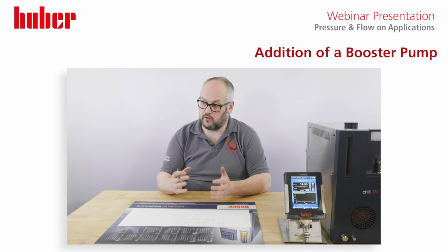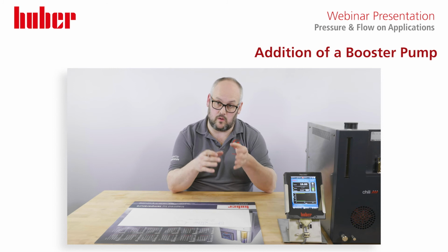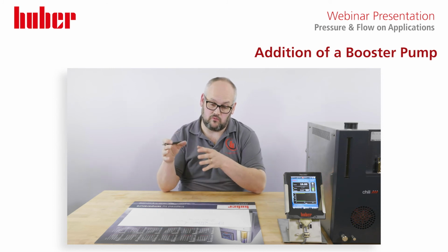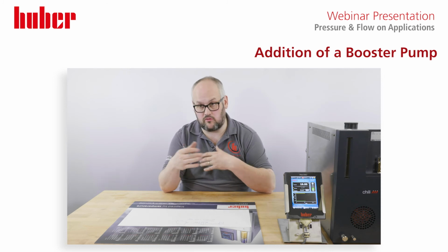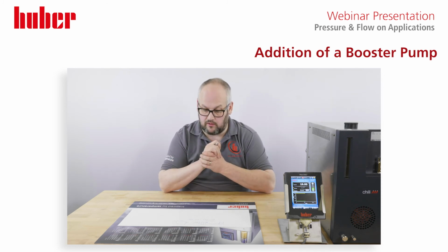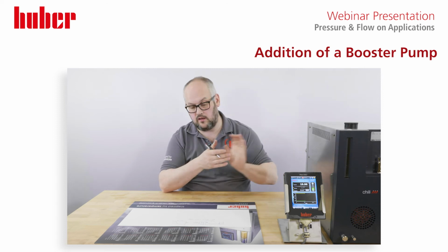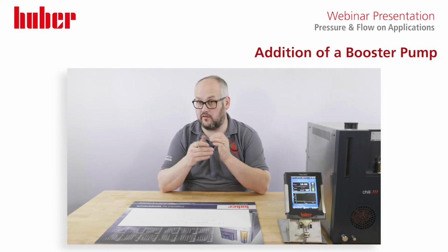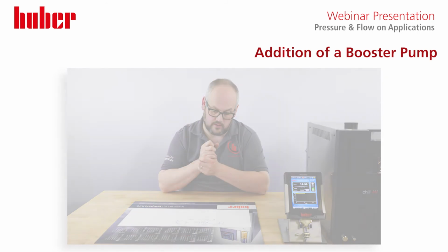So if you're getting a booster pump for your system, bear in mind that if you're applying cooling to a system, that heat will knock out a proportion of your cooling. It's only between 300 and 600 watts, but it's something to bear in mind. Obviously, if you're using a heating TCU like a Chili, it's not going to affect it much because it's adding extra heat. It's adding to the function of the unit.